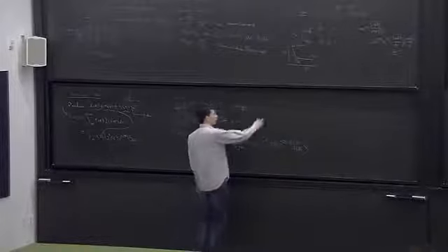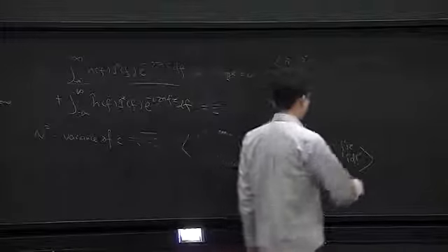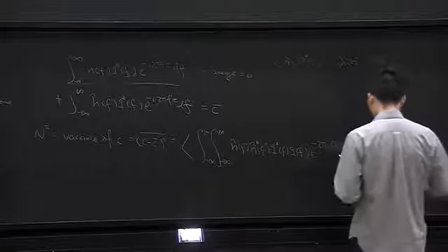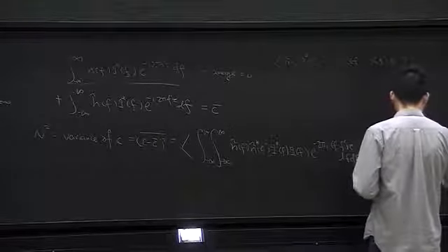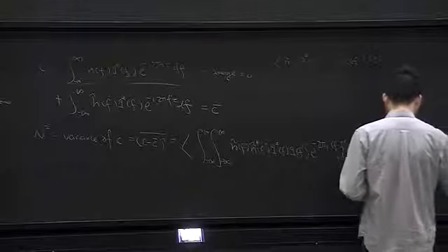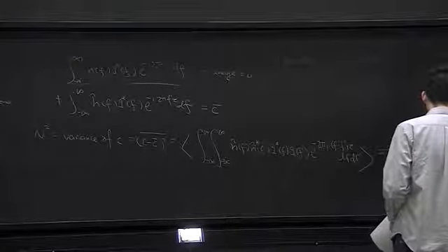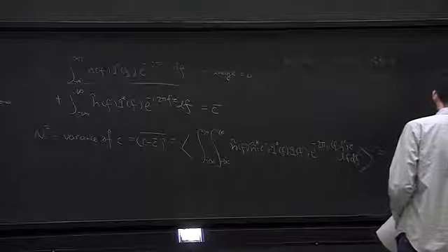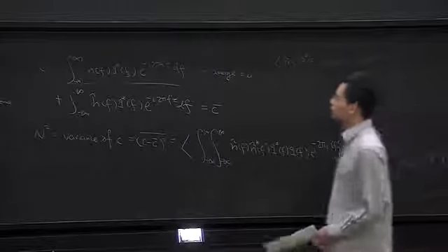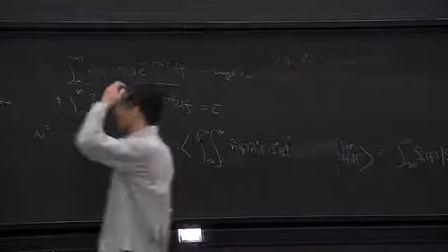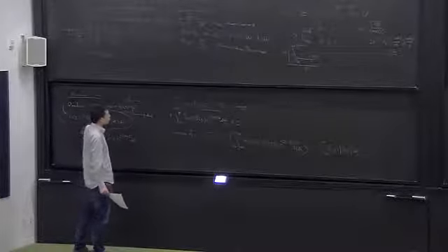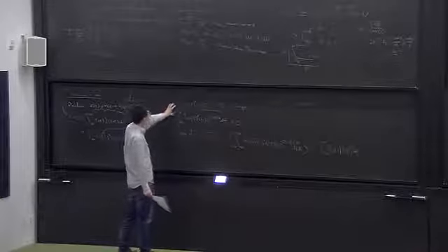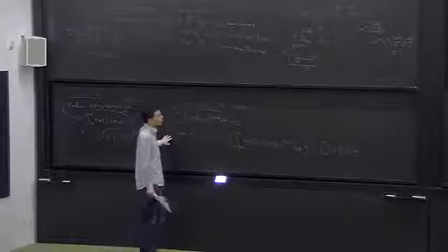So you can plug this in, and this will equal the spectral density S_n(f) times |Q(f)|^2 df. So I've defined this correlation operation, obtained this quantity C, which has two pieces, a constant piece and a noise piece, and I just compute the variance of the noise.